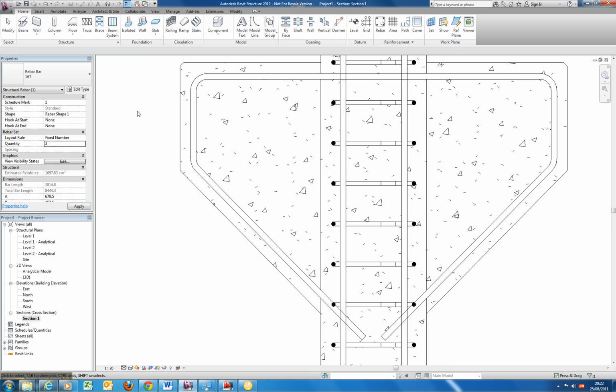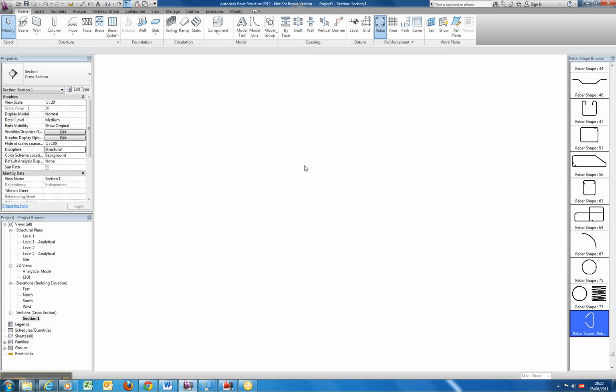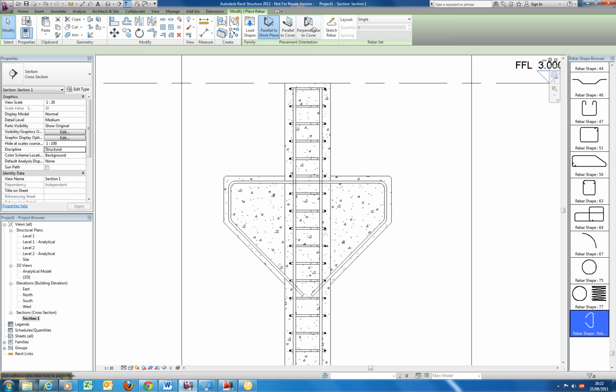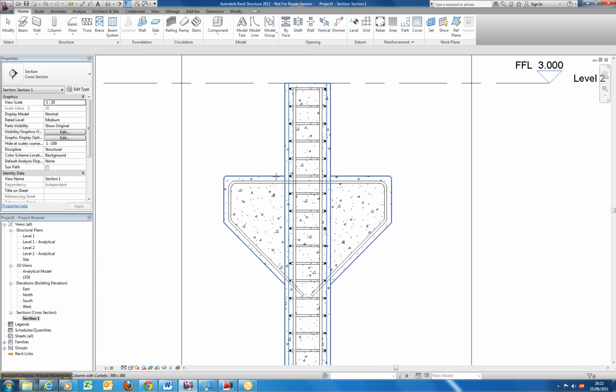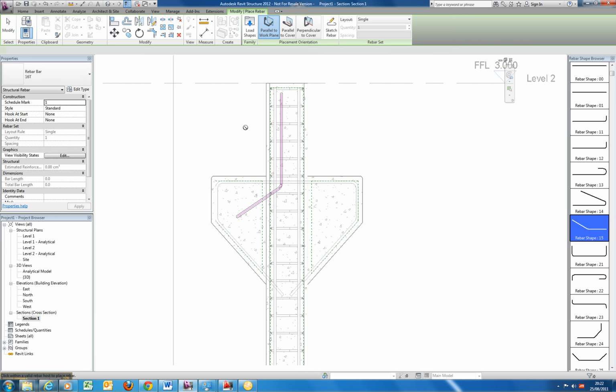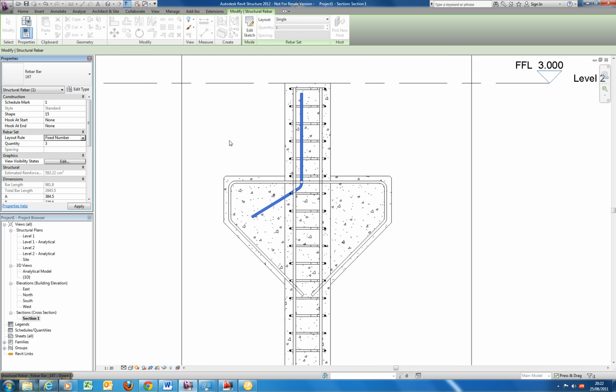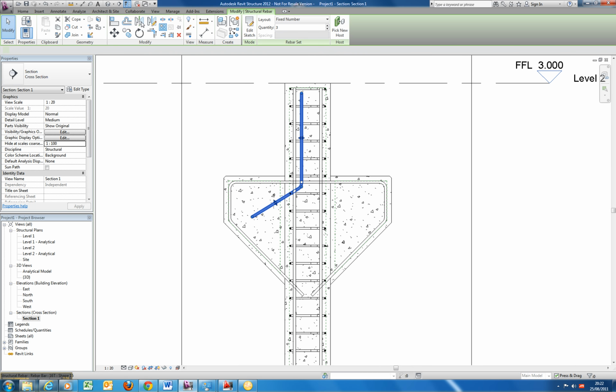Finally, I'll add one more custom area in from the corbel to make sure there's a good attachment. Add a bit of rebar. We're going to sketch it. From this point, we'll take it across again, T16s. Finish it out. We'll add 3 of them in, same as last time. So we'll say it's a fixed number of 3, and again we're going to mirror on the axis.